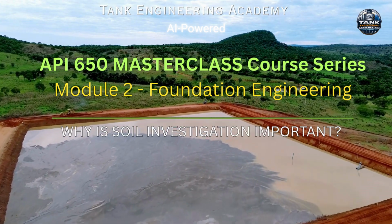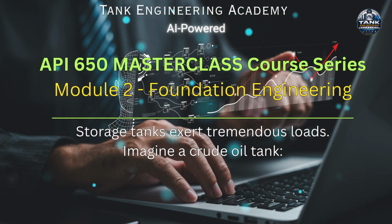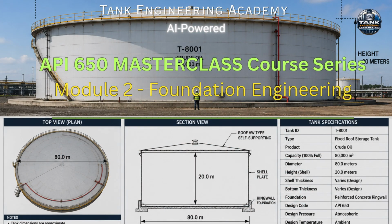Why is soil investigation important? Storage tanks exert tremendous loads. Imagine a crude oil tank, diameter 80 meters, height 20 meters, product weight more than 80,000 tons. All of that weight is transferred into the foundation. If the soil cannot safely support the load, the entire tank will settle.